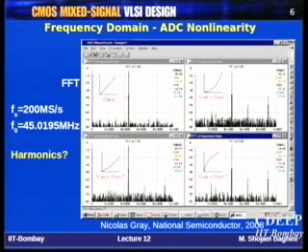when you do FFT, what is FFT? FFT is essentially based on DFT, the discrete Fourier transform. When you sample a signal, you will have an n-point DFT, and then it will be converted into an n-point FFT. Now, suppose you take a window in the time domain and sample a signal. As you increase the number of samples in this time interval, without changing your window width, just increasing the number of samples, what do you expect to see with respect to the quality of the sampling?